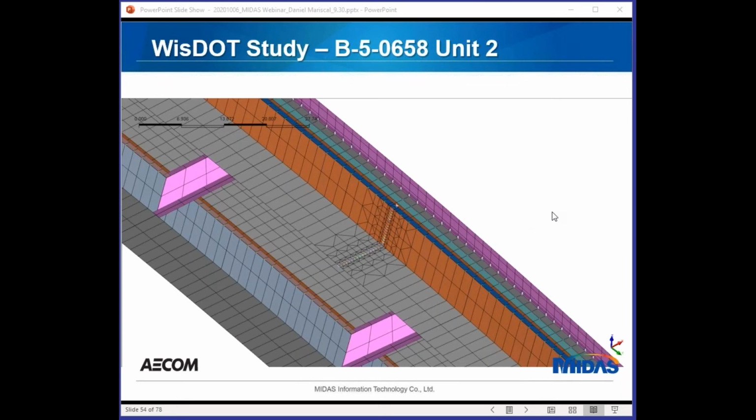And what we did, in order to mimic a progressive failure, was start unbuttoning the bottom flange node at the middle. There were basically 2 nodes in the same space. One node belonged to the left side of the girder, and the other node belonged to the right side of the girder, and they were connected with an infinitely rigid spring.